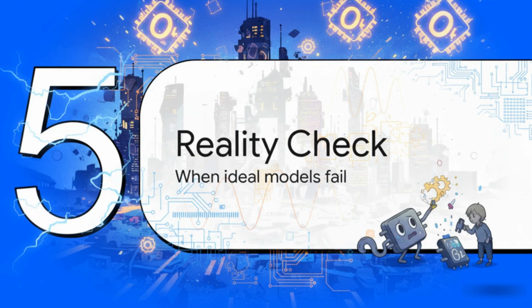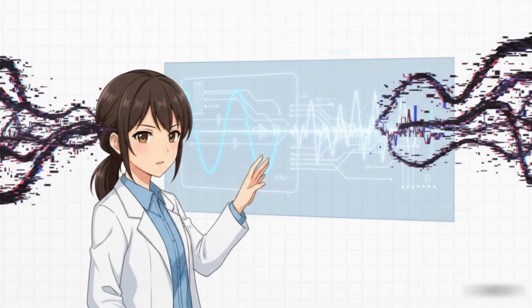So far, we've been living in this perfect, beautiful world of the ideal op-amp. But of course, in the real world, no component is perfect. And this is why that ideal model is so important. Not because it's true, but because it gives us a perfect blueprint to compare against. Good engineering is all about understanding how a real op-amp messes up that blueprint and then figuring out how to deal with it. So, in the real world, the gain isn't actually infinite, and it starts to struggle at really high frequencies. That's what we call finite bandwidth.